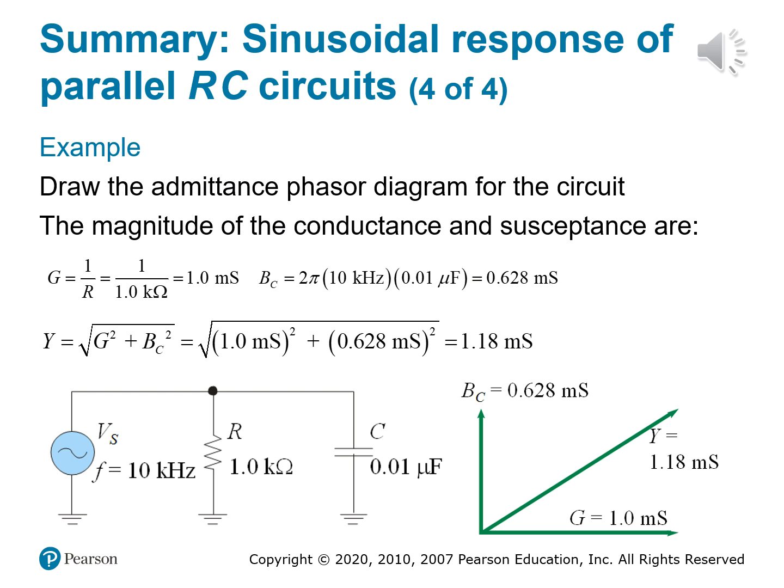So let's compare this to what we talked about in the inductor episodes. And if you have not seen the inductor episodes, please go watch them. You should have, because that came before this. But back then, when we covered the parallel RL circuits, we had inductive susceptance, B sub L, and that was plotted downward on the negative j axis. Here, B sub C is plotted upwards on the positive j axis. So it's in the opposite direction. Same math, same rules. We just flip the orientation based on the component's behavior.